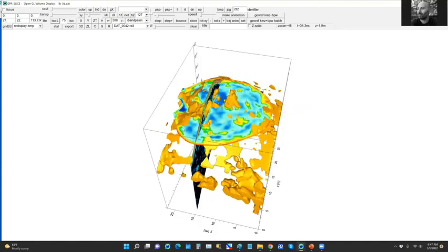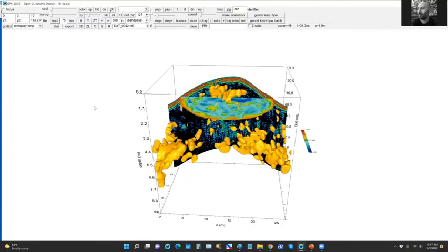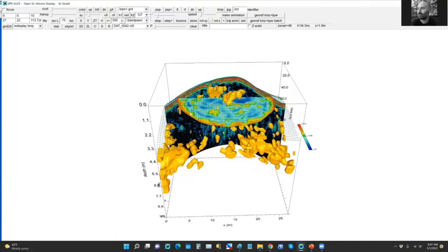And for the isosurfaces, if you want to take away some of the top surface reflections, you can say, well, let's start the isosurfaces at around 10 nanoseconds, and you'll be able to take off some of the top surface reflections and look a little bit deeper in there. You can store that to the screen, and you can also get on the topographic grid. We can put that on as a net. So you can have that all there in 3D.